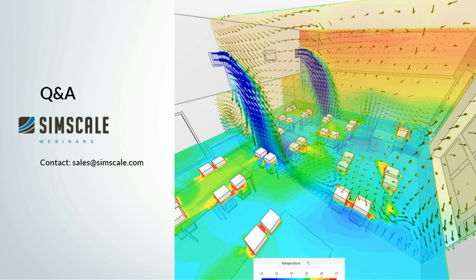Yes, one comment on this on top. With SimScale, we have the ability to not only model the inside of the building, but also the external surroundings. For this, we would use a different solver, which is a lattice-Boltzmann-based solver called Pacefish. And with it, we can analyze up to 36 different wind directions for a typical year. Based on these results, we can get the pressure coefficients on the different window openings. And then we can use the pressures from this simulation as a boundary condition, alternatively, for the indoor CFD analysis. We have another case study on our website, which you can have a look at, where exactly this strategy was used.